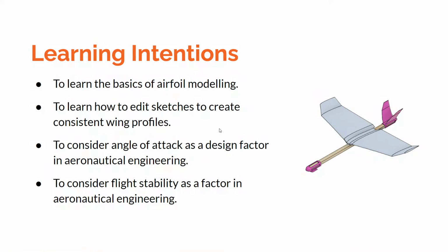So our learning intentions are to learn the basics of airfoil modeling. We won't be doing this from scratch. We'll be using the NACA sketch plugin for Fusion 360. We'll learn how to edit sketches to create a consistent wing profile.